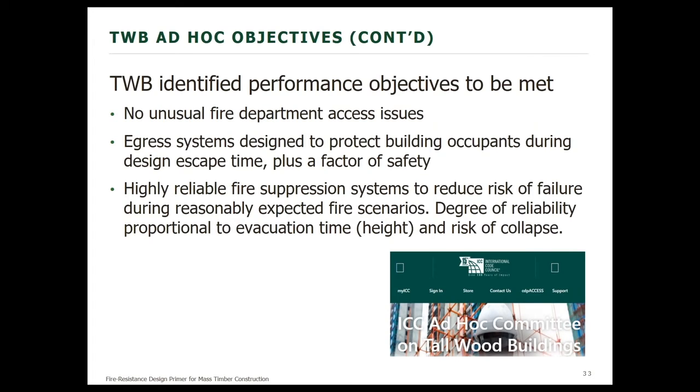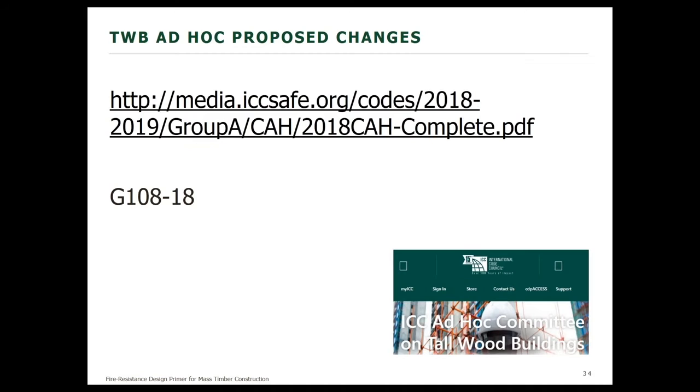And last but not least, the last set: no unusual fire department access issues, making sure that the fire department is not adversely affected due to the mass. Egress systems designed to protect public occupants during design time escape, plus a factor of safety. And then highly reliable fire protection suppression systems to reduce the risk of failure during reasonably expected fire scenarios.